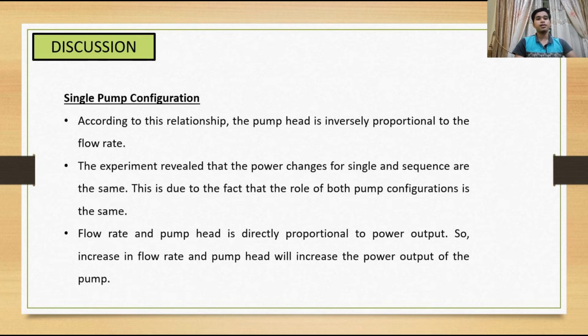The first one is the single pump. Our experiment tells us about the effects of pressure drop, pump strength, and performance of different pump configurations. In the experiment, we build and test single, series, and parallel pumps. The data from these three experiments is used to create a graph of pump output.